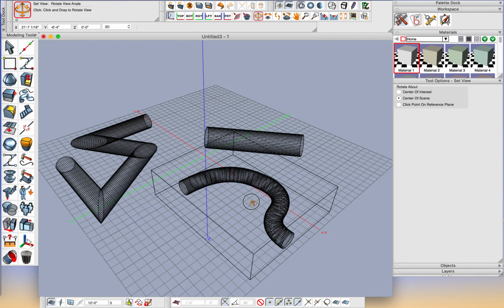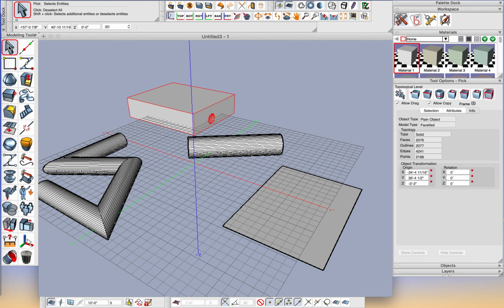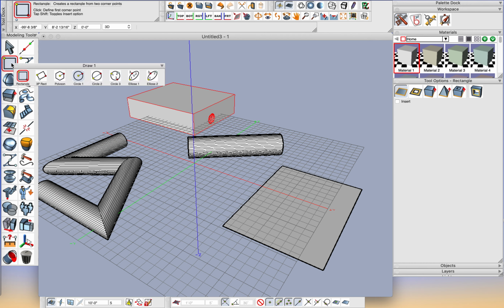Now, I'm just going to move this out of the way for a second. You don't have to create just a raw drawing path. You can actually create a 2D object, 2D, not 3D, and you can extrude around the corners of this object itself. So if you wanted to have your extrusion along a rectangle, the shortcut way would be to first draw the rectangle, then draw your shape.